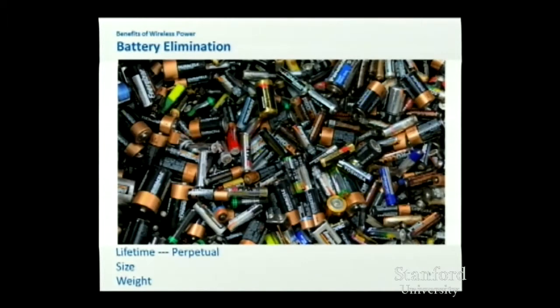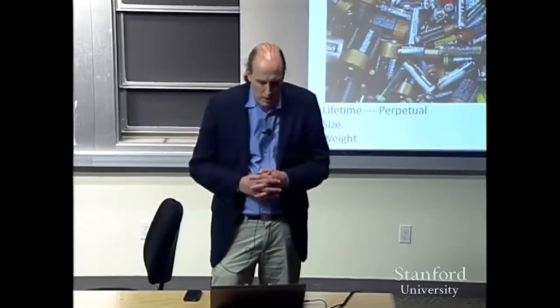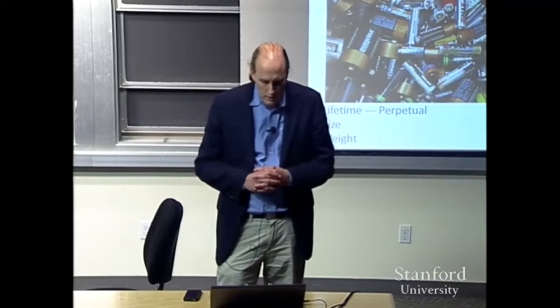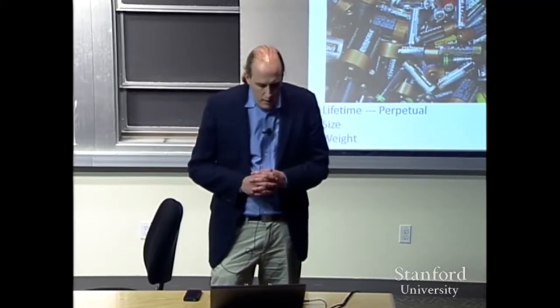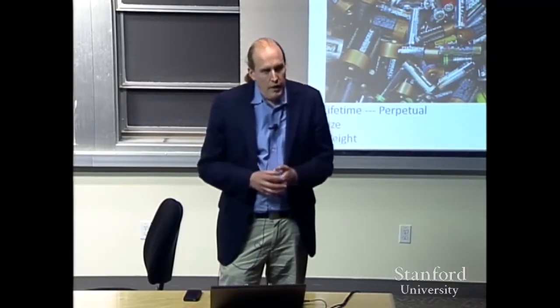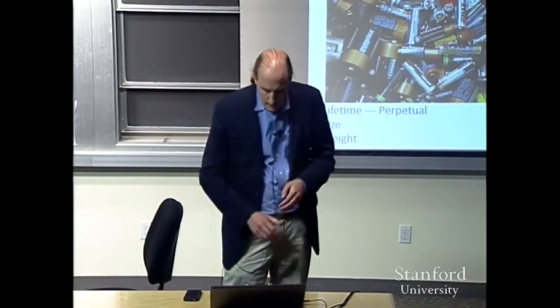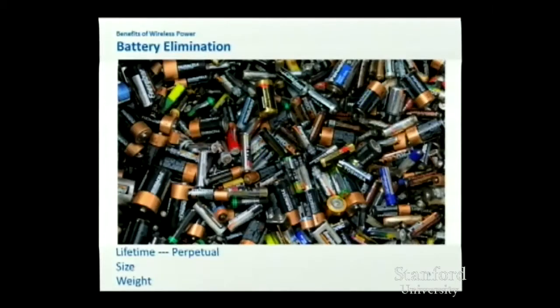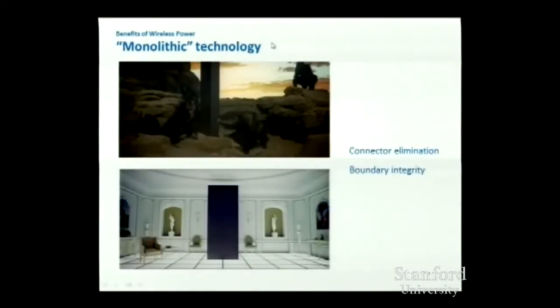And if you think about what are the benefits of getting rid of batteries more specifically, one is your device can potentially have a perpetual lifetime. If it's getting the RF live, then you may be able to eliminate the battery altogether and not worry about it dying. If you can eliminate the battery, you can often reduce the size, so sometimes we're in a volume constrained situation. And of course you can get rid of weight as well, and you'll see some applications today where the weight constraint is really the benefit of wireless power, or removing the weight constraint.